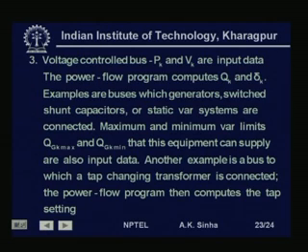The main reason for this is, at these bus bars, since we have reactive power control available, we try to keep the voltage magnitude controlled at some specified value, and since these are also generator bus bars, the real power at these bus bars is known.